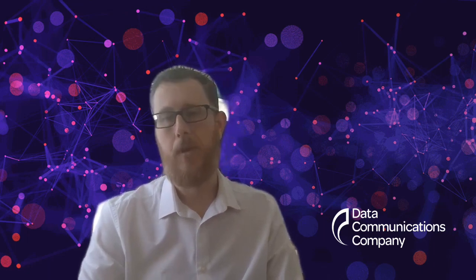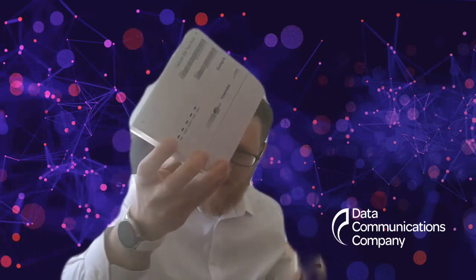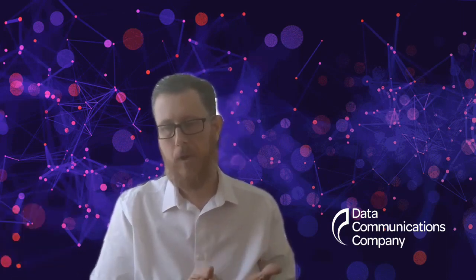The very last question from Raj is how do smart meters actually communicate back? Does it have a dedicated radio link, or 3G or 4G or something else? Yeah, great question. So the communications hub is what will sit in a home, and actually I've got one here. It looks like this. So that's a communications hub, and it's basically like a modem. It provides a local area network, or a home area network, a HAN, in the home, and it also connects wirelessly to a WAN, a wide area network, either through long range radio if you're in the north and Scotland, or if you're in the central and south regions of Great Britain, you will be on a cellular solution. So that's a 2G, 3G connection.